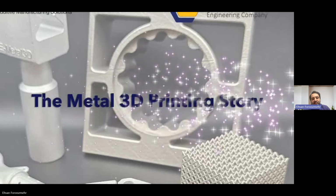The next step is the machine that is going to run. The laser is scanning the surface, and a very thin layer of powder is being melted. What you're watching is a very high-speed laser beam moving at over 1000 millimeters per second, melting the stainless steel and welding it to the previous layer. Once this layer is done, the coater brings another layer of powder. What you don't see here is that this section goes down 60 microns, which is very small, so we don't see it at this resolution.